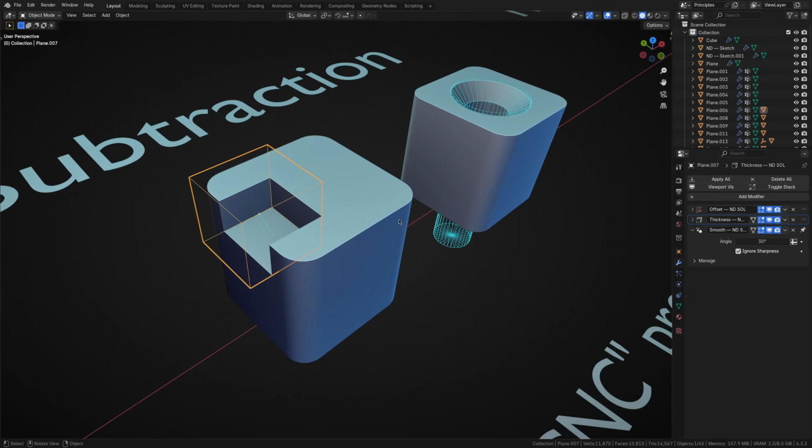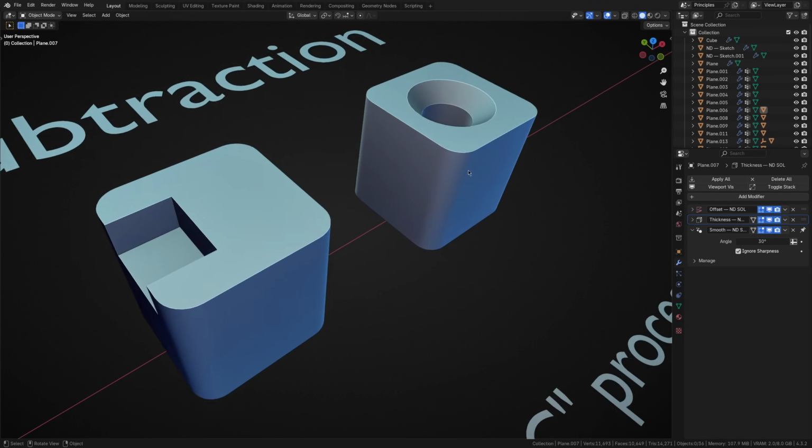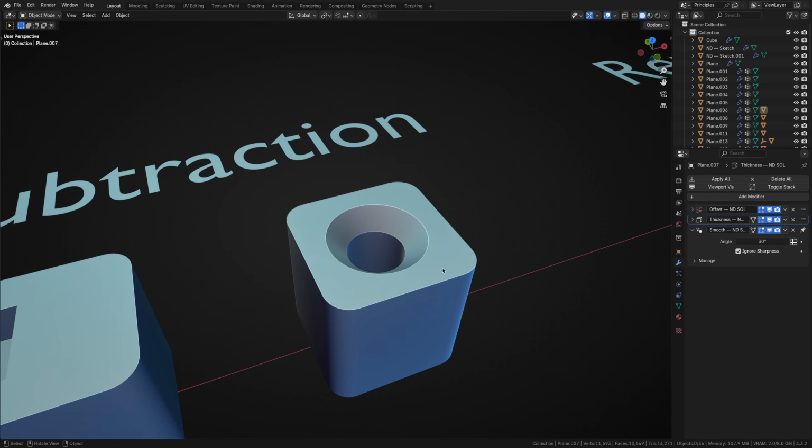I want to take a look at another subtractive example to highlight another important point. This next example shows a similar looking base object with a hole drilled out of the middle. One aspect that's particularly interesting about this hole is that it has a countersink. In previous examples, I mentioned that when you see a bevel, you can typically undo it. However, if we imagine the shape coming from a plane, where do the necessary edges exist to form this chamfer? The entire top face of this object would be flat if we extruded it from a plane.